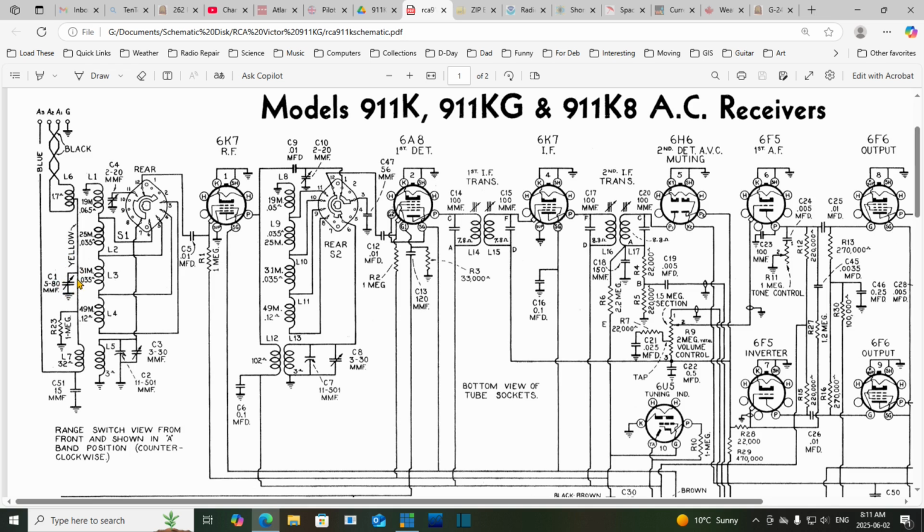Here's an adjustable capacitor here. Here's one here, 15 picofarads. So, picofarad capacitors are probably of the type that's really not important to change out, not unless you really have a strong indication there's something afoot with it. There's another adjustable capacitor, and then here's the first one. So all the signal from the antenna, after passing through this transformer arrangement and the switch, all of it goes through this capacitor to get into the rest of the radio. So if this guy's bad, everything's bad. Of course, the radio's working fairly well, so how bad can any of these really be?